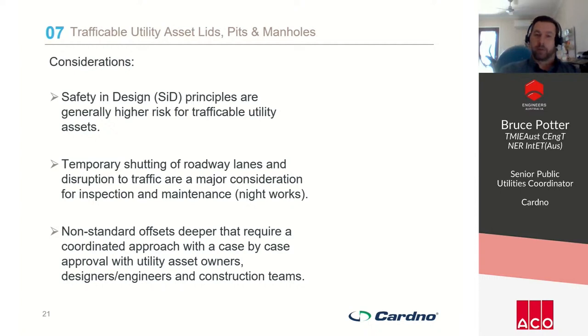And if you're in areas where you've got multiple different asset owners, so a council versus a main roads entity, again, you've got coordination with a lot of these asset owners and operators and authorities to come together. Sometimes the assets themselves are non-standard. They're much deeper than their counterparts on verges, and that is to counteract the traffic loading. And again, there's a coordination approach between the approval of asset owners and authorities, designers, engineers, and construction teams.